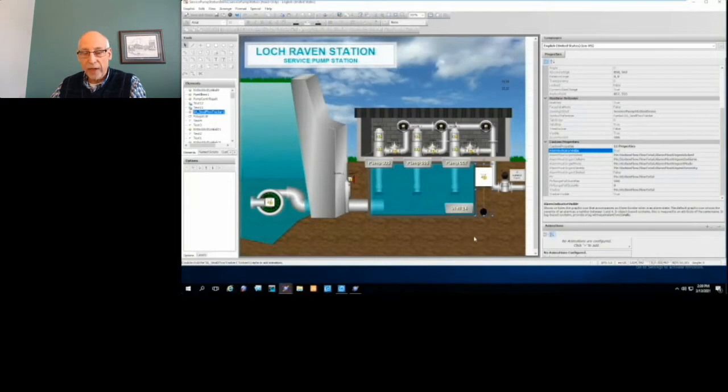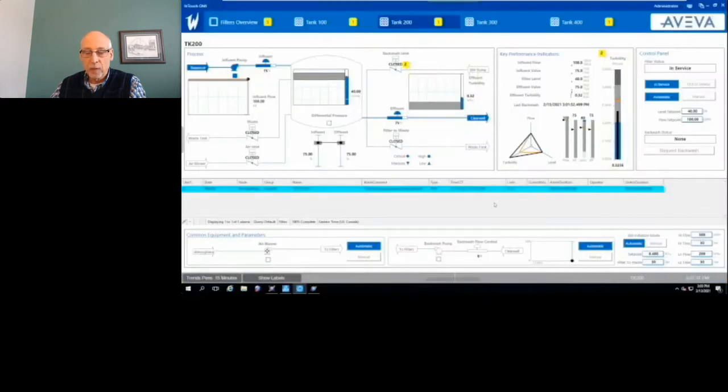I also had one of the newer Orchestra graphics, the situational awareness graphic library symbols, on the screen, and that has a built-in function to enable that alarm banner. So if I click on that indicator I have here, I basically have to turn on that property to enable that. So here's another use case for the alarm border animation.